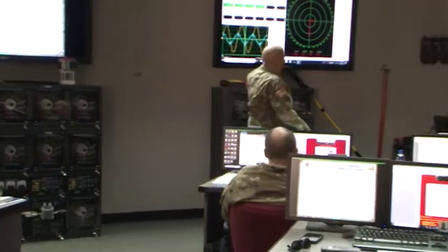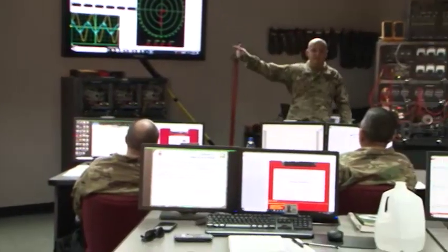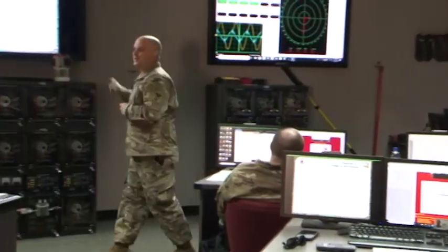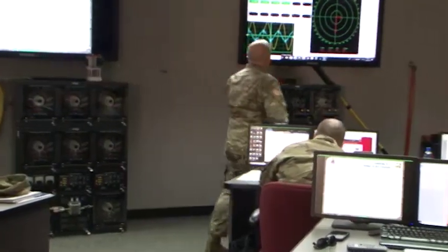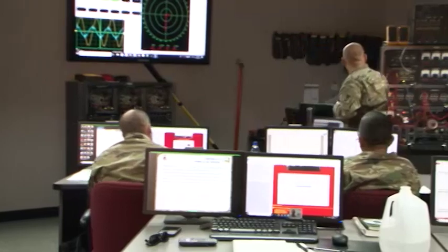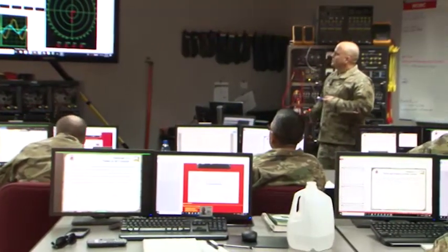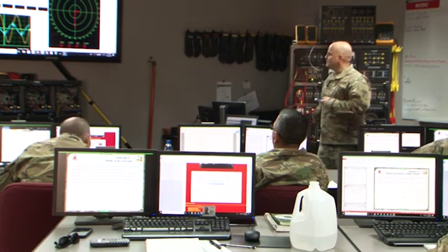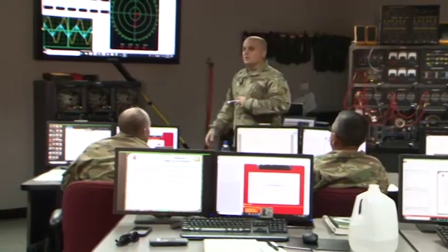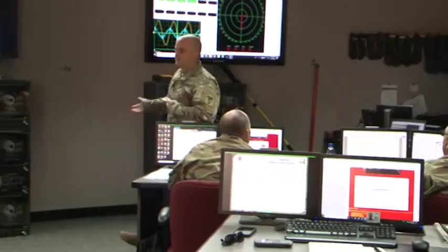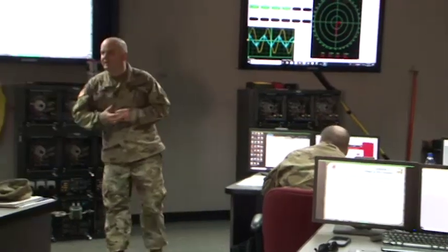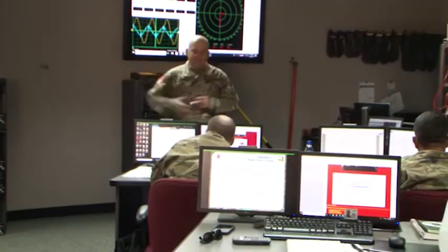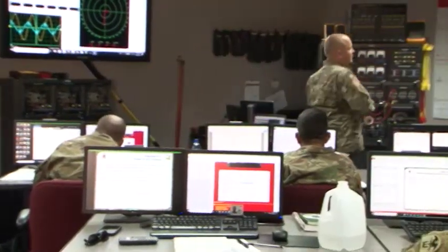Okay, so now what's happening? Notice on here now, we're getting a perfect 90-degree angular relationship there, correct? Yes. Perfectly 90. Notice on the inductor, it wasn't perfectly 90. That's going to kind of play into a part here in a minute when I show you something, okay? All right, so if I do the same thing here, dial up, dial down, right? It is what it is, okay? All right, this is simple enough, and we can use Ohm's law. We learned that we could do the capacitive reactance and the inductive reactance. Those give us an ohmic value. They're a complex number, okay, which means it's that J, right? And we can solve for what the current should be.